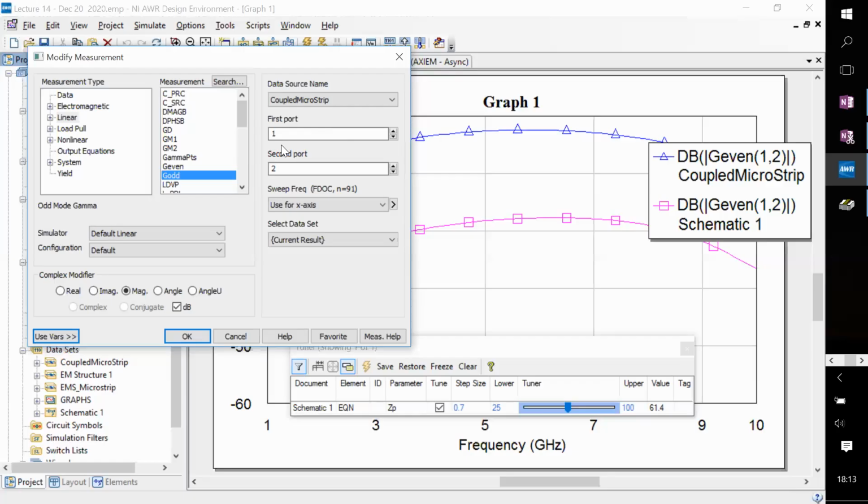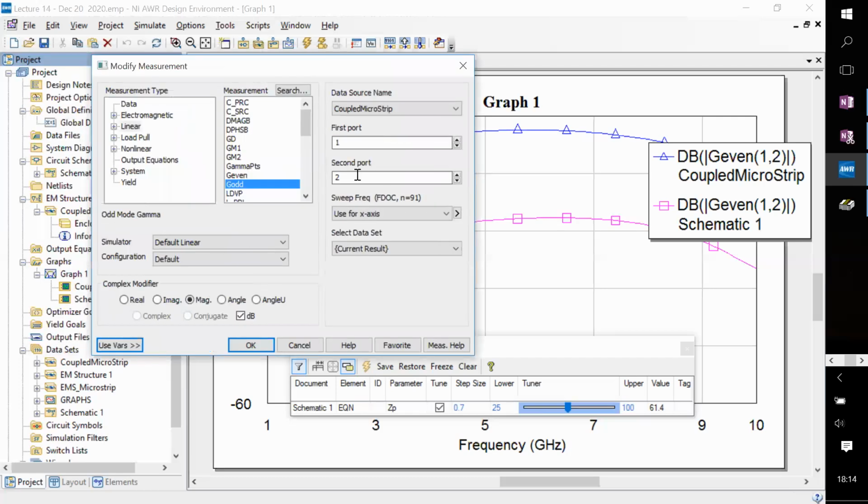You're not going to get a mixture of both, so the returned signal will also be essentially even mode. Not always necessary, because if the boundary condition on the other side is not symmetric, in the sense that it doesn't maintain the symmetry of the even or odd mode, you can actually get mode conversion happening. I'm not really sure exactly how Microwave Office does it internally, but I'll explain what it means to have this different symmetry.